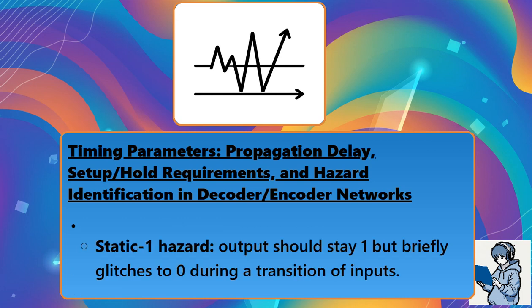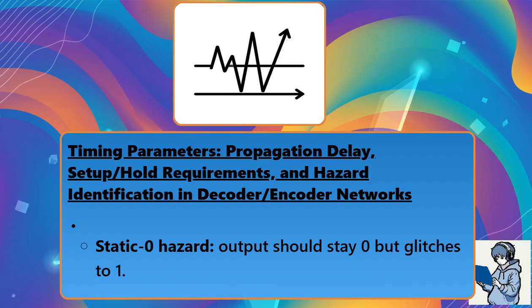Hazards. Static 1 hazard: output should stay 1 but briefly glitches to 0 during a transition of inputs. Static 0 hazard: output should stay 0 but glitches to 1.